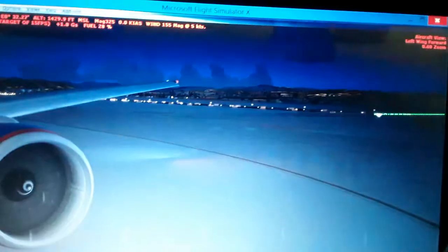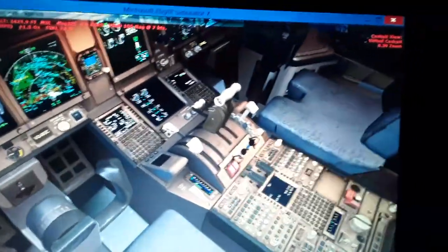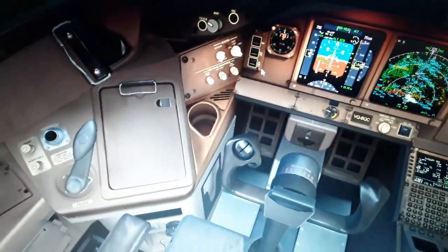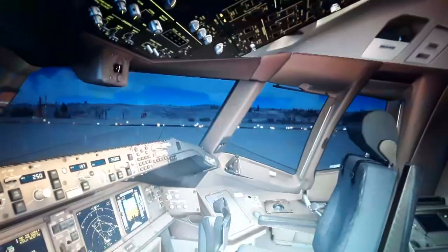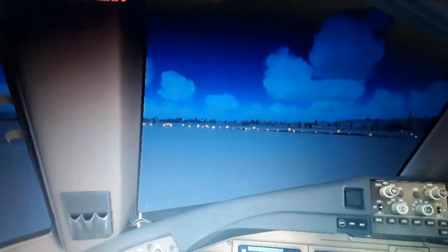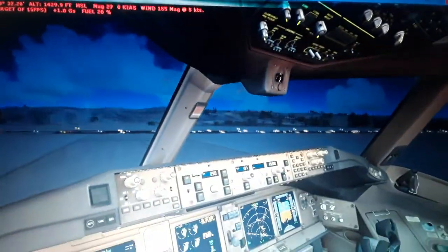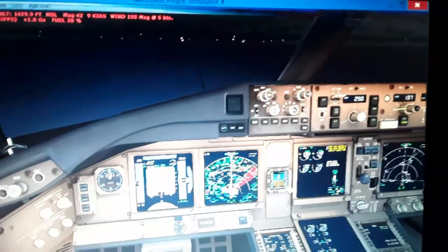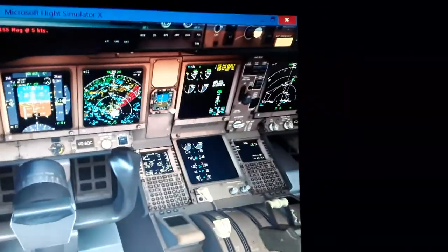So here we are. We have to taxi into the runway. Advance some thrust levers here. Disarm the parking brakes and use the tiller here. This tiller to move the forward wheel, the nose wheel steering. So we have directional control on the ground using the tiller and the rudder pedals for the nose wheel. We have to fly the aircraft for about 20 minutes, so advance the thrust levers again.